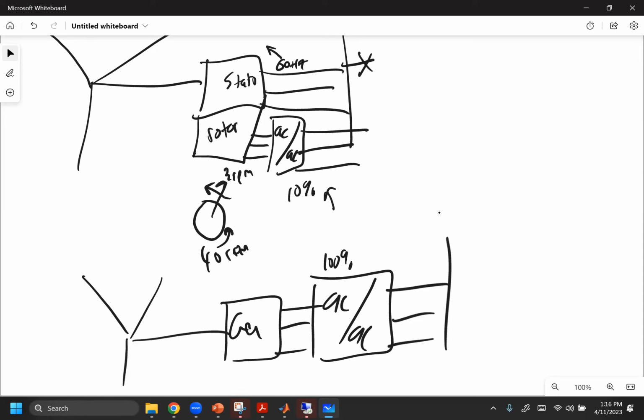It's a compromise, so you don't have to have a mechanical gearbox that you have to keep refilling oil on. All wind turbines have gearboxes, because to get a generator that can handle the torque that has 50 poles, it would be the size of this room. They're huge. You can't have that at the top of a tower that's 250, 300 feet in the air. It's just not practical.